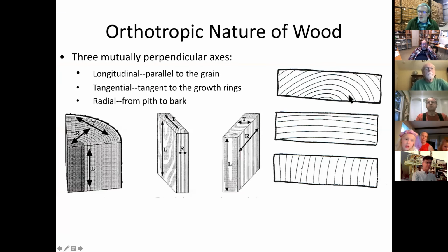Okay, so right here, this is typically what you're going to see. More of the plain sawn wood that you're going to pick up is probably going to be closer to this piece here. Maybe not as drastic. Let's hope not quite as drastic as this. But this would be cut out of a small diameter log. You can see the pith, which is the center of the tree, is going to be down here. The bark is going to be up here. Now tell me, the width of this board, is it plain sawn or is it quarter sawn? Well, it's a plain sawn board. I told you that. Is it going to be more tangential on the top or more quarter sawn?